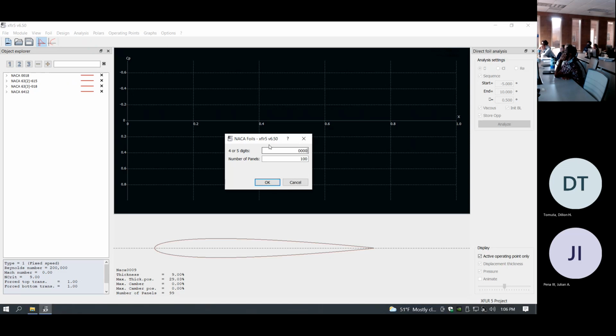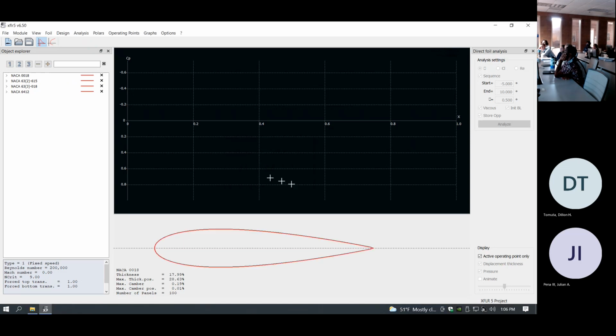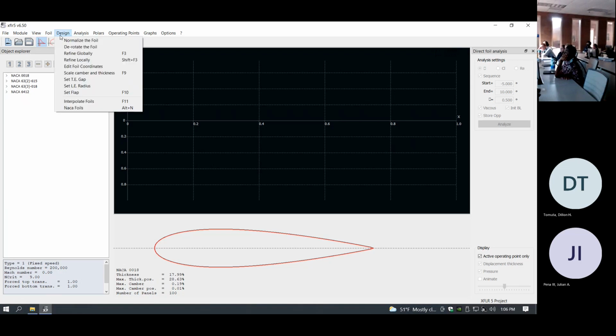What I had to do to get my non-conventional airfoils, my NACA 6 series, is you can go on a website Dr. H provided called airfoiltools.com, and you can essentially look for an airfoil that you want. You can download the data points as a file, and then there's a certain command you can use to take a data file you can download online and input it into XFoil.